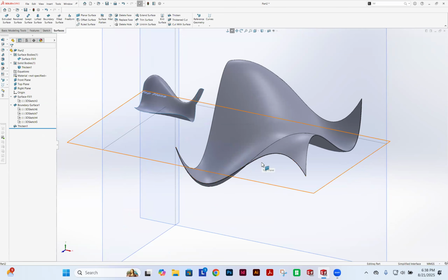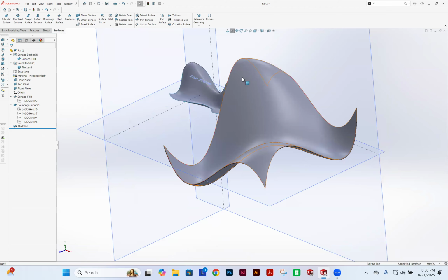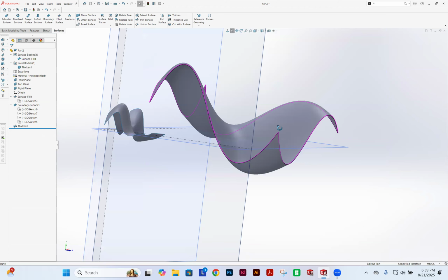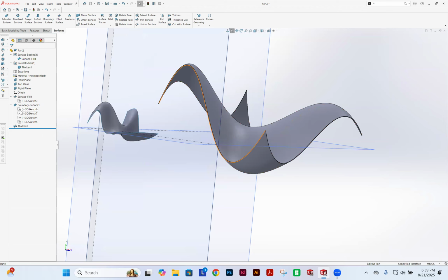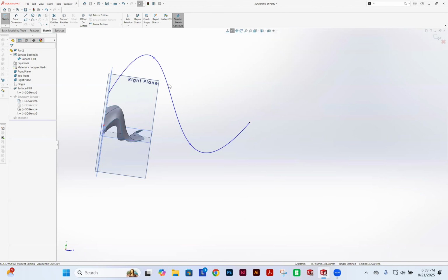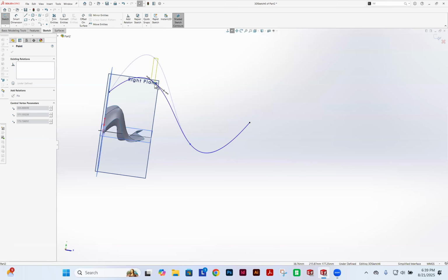As you know, the beauty of SolidWorks, as opposed to some of the other 3D programs that we have at our disposal, is that you can go back and change anything in the history tree, the feature tree over on the left. So let's say, for example, I wanted some of these curves to not be quite so drastic as they are right now, these roller coaster-like shapes. I just need to find that particular curve that I want to adjust, that 3D sketch. You click on it and then choose the little pencil, grid paper looking thing for edit sketch. So now that's my sketch there, which I can adjust the curvature of, greatly reduce it.